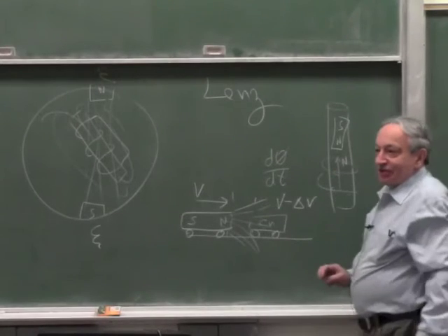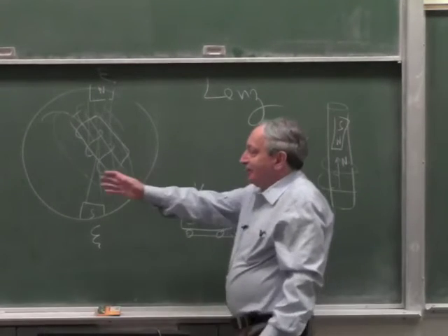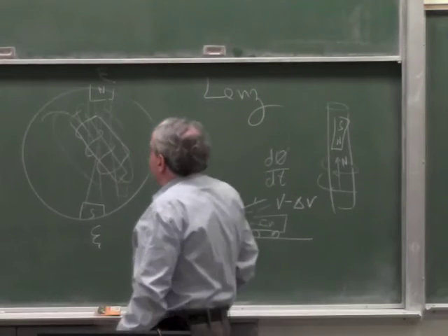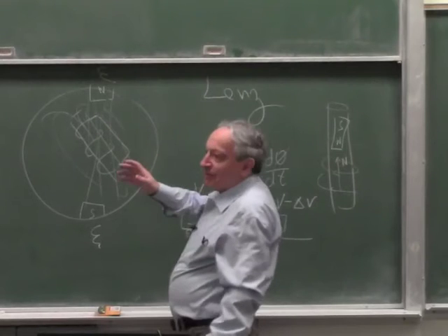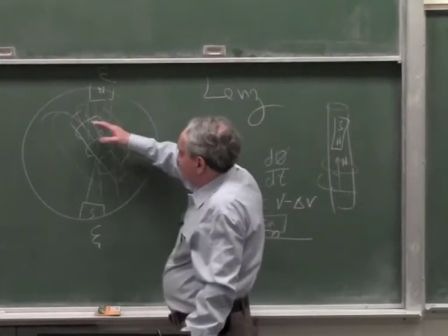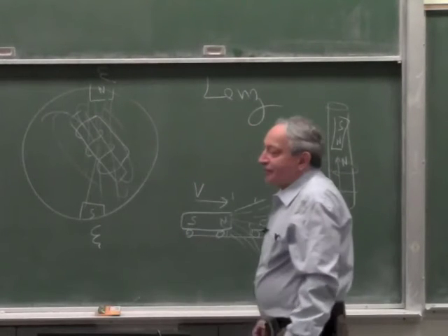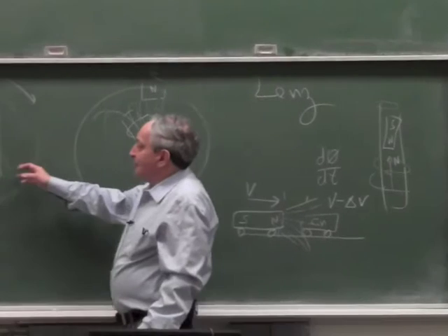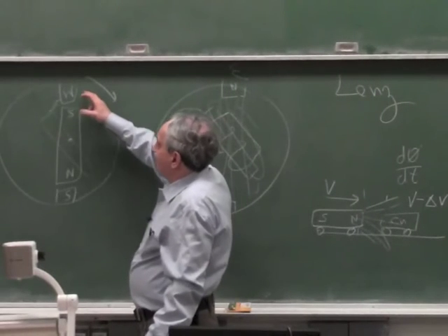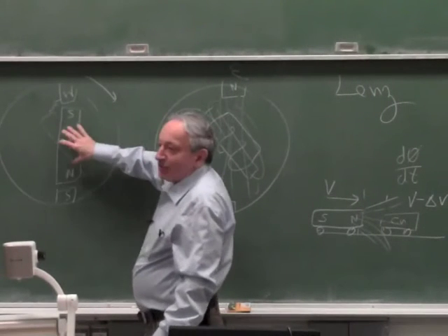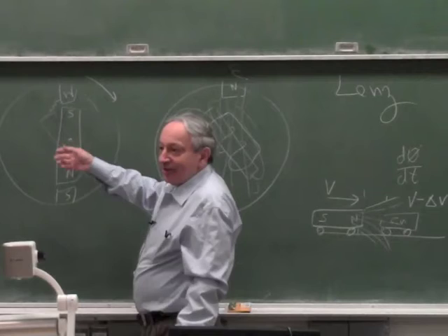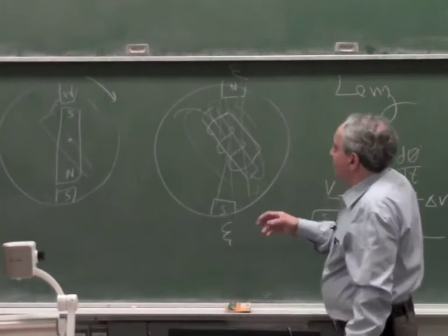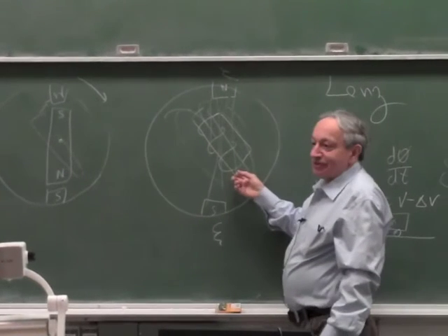So the effect is the same as here, in the sense that you have a power angle, you have all the same effects. Actually, in this case, not a power angle, it's continuous slip. But the only difference is that in a synchronous motor, the magnetic field attracts the opposite poles of the rotor and drags them along. And here, the rotating magnetic field actually repels the rotor.